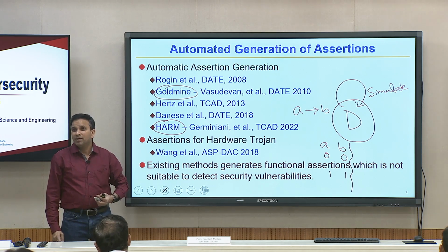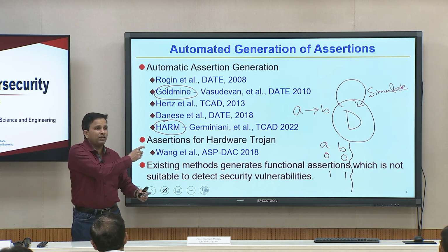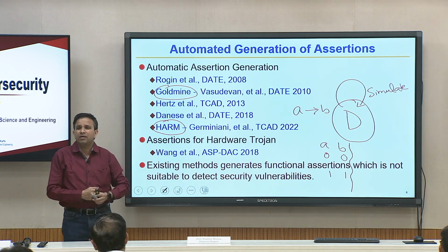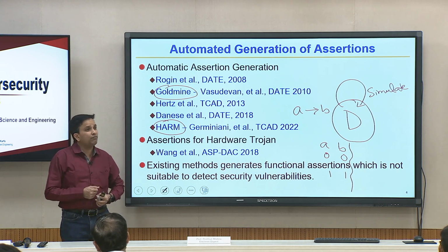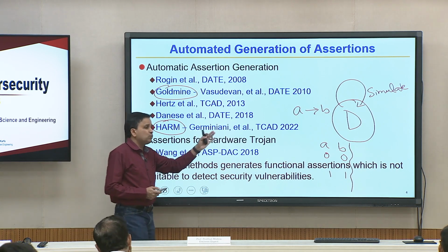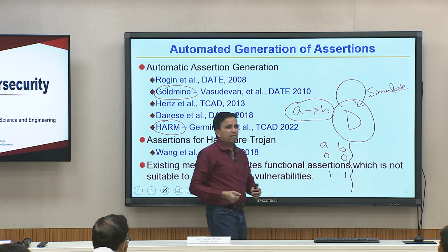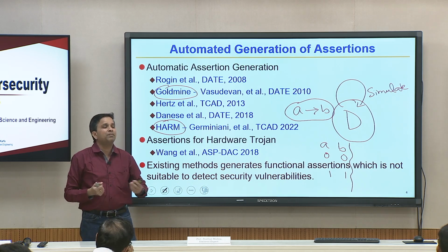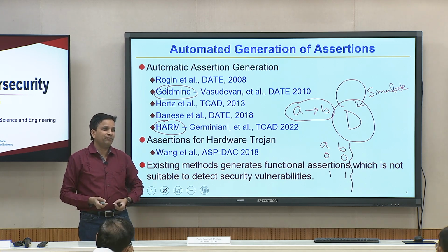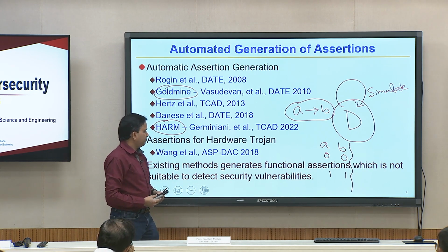Now, as you realize, up to the time it ran, that relationship exists. This is a simple relationship I talked about, but it could be a really complicated relationship, a big equation. Is it possible that if you run 10 minutes more, this relationship will fail? That is possible. That is why, once these tools figure out this kind of invariant relationship, they do model checking to check whether it is true for eternity, and then that becomes an assertion. So, this is the story of generating functional assertions.